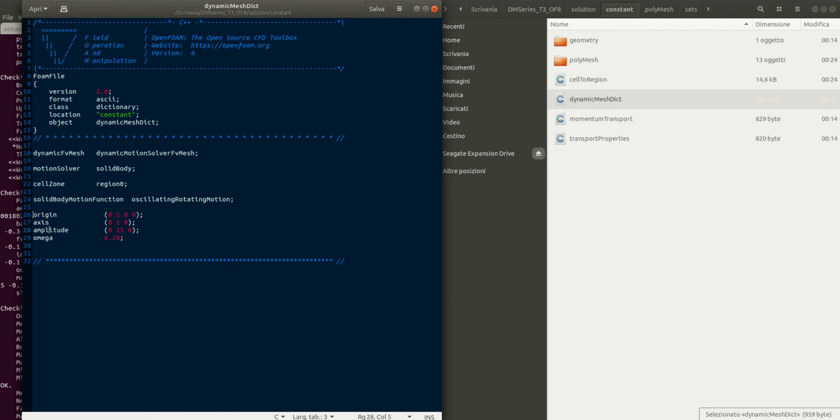So I put the center of the cylinder at the middle chord of the airfoil, so I'll put the origin of the rotation at the same point, because if I don't do this, the inner portion will penetrate the outer portion while rotating, because it will be rotating not symmetrically, with eccentricity, let's say.